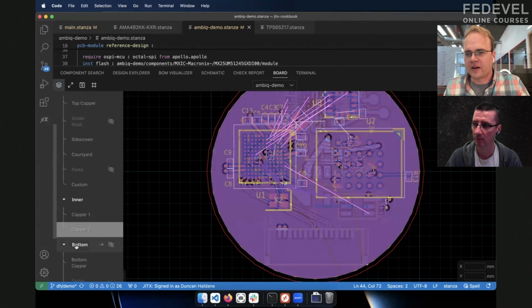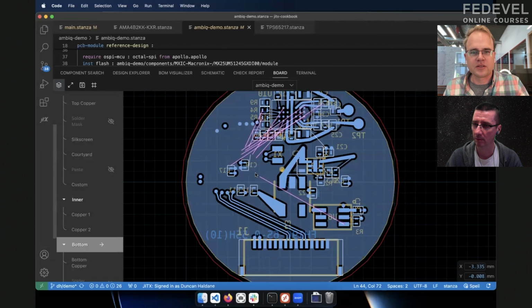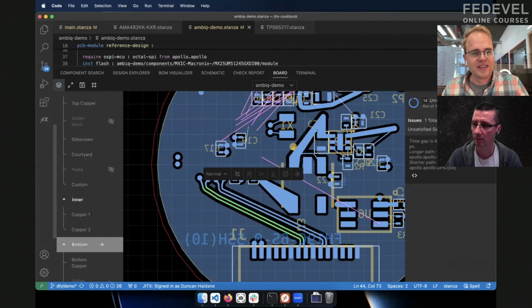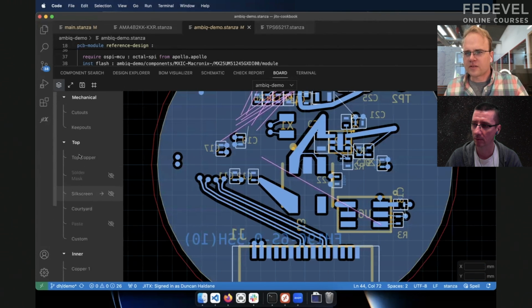And then bottom layer, we've got our wireless charging circuit, power regulation, that kind of thing. Our differential pairs for MIPI. And these are all happy. So I don't have any messages here, which means it's looking good. All the skew constraints are met. So yeah, if I was going to finish that off, let's see.